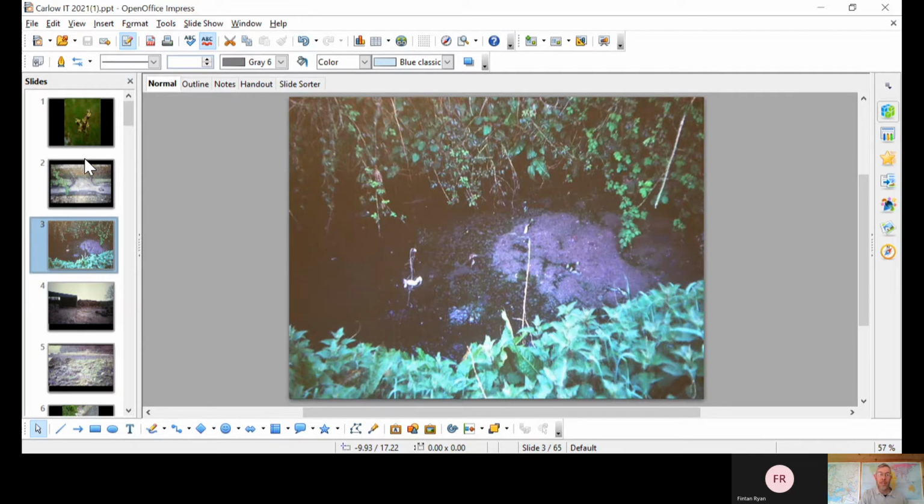The other is BOD, the biochemical oxygen demand within the water. And that's basically a measure of the food value that's in the water. So the higher the BOD, the more the microbes can have a party, basically, and feed on it. Now, if you overfeed the microbes, they'll breathe too much oxygen, they'll take in oxygen and strip it from the water. So that was the reason for the fish kills in the late 1980s, when there was silage effluent and the like getting into watercourses around the country.